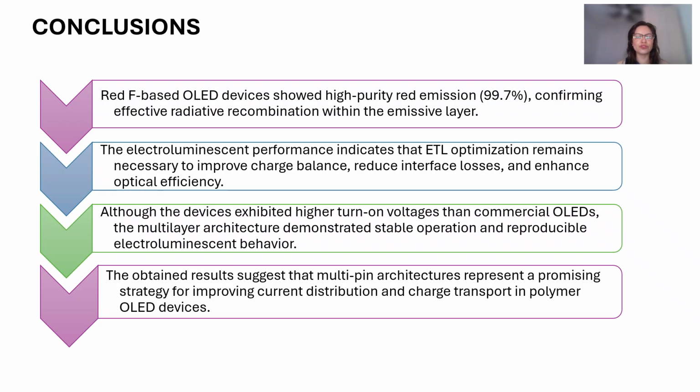Now, the conclusions are the following. First, REDF-based OLED devices showed high purity red emission, confirming effective radiative recombination within the emissive layer. Second, the electroluminescent performance indicates that ETL optimization remains necessary to improve charge balance, reduce interface losses, and enhance optical efficiency.